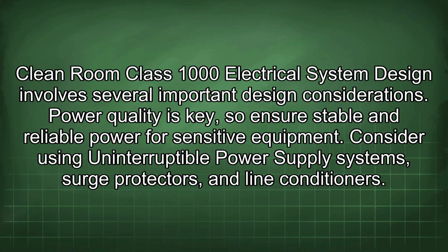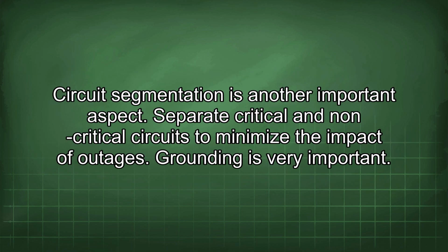Cleanroom Class 1000 electrical system design involves several important design considerations. Power quality is key, so ensure stable and reliable power for sensitive equipment. Consider using uninterruptible power supply systems, surge protectors, and line conditioners. Circuit segmentation is another important aspect. Separate critical and non-critical circuits to minimize the impact of outages.